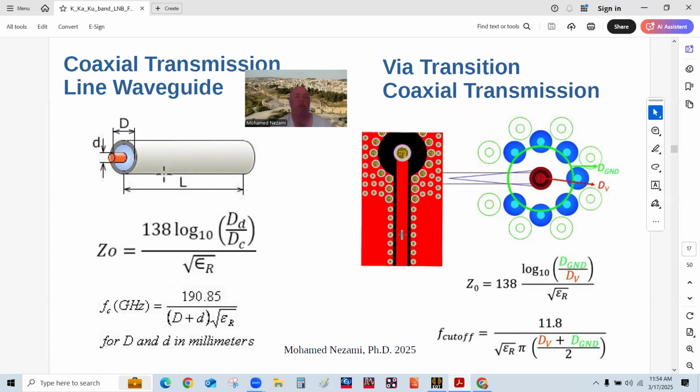This is not off the shelf. I mean, you're putting in an inner pin in here, and then there's the housing itself, the aluminum housing, which has a tube where this one goes in, and you can insulate that via a dielectric Teflon material insulator. And so the characteristic impedance is governed by this, and the cutoff frequency is governed by this,